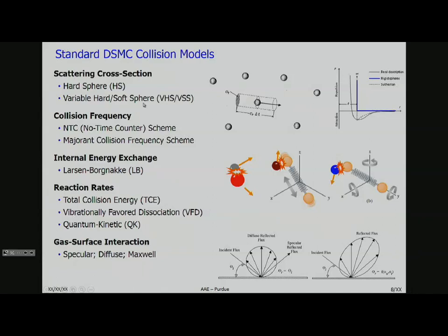Next there is the internal energy exchange. Obviously it's very important. Two particles collide. What are their new vibrational, translational, and rotational temperatures, or energies rather? And that is done with the Larsen-Borgnakke method, which I believe is the most used in basically every DSMC solver out there.